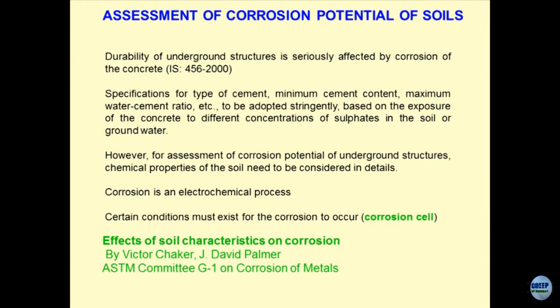So, it will all depend upon the type of cement. I hope you understand what is the meaning of the type of the cement: minimum cement content, maximum water cement ratio, and what is the exposure condition to which the concrete is getting exposed, and what are the sulphate and chloride contents which are prevailing in the ground water. So, then accordingly I can choose the cement.